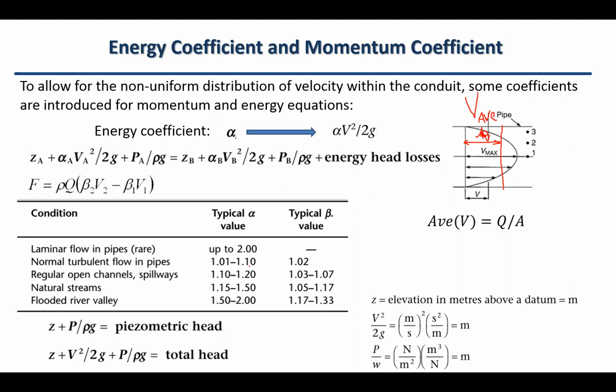So just bear in mind, we just learned the total head in 3 terms: Z, V squared over 2g, and P over rho g as total head. Just bear in mind the piezometric head that we can calculate by using the piezometer or the standing pipe to calculate the pressure head. So it has 2 terms, elevation head and pressure head. So this normally shows the pressure head, but if you have a constant elevation head relative to the reference line, we can say this is the piezometric head. Okay, so that's a total head as well.